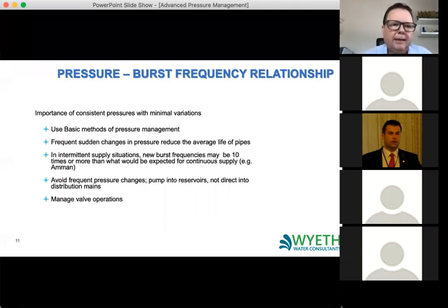When we're also looking at leakage volume, that is the first thing that we can look at with pressure management. But as I mentioned, burst frequency is another factor that a lot of utilities have to cope with. Especially utilities in places like Asia, where I work, you will often go to these utilities and they will have thousands of bursts or leaks that they're actually having to find and repair on a monthly basis. And a lot of those leaks are new ones that have occurred in the last month. So that's what we would call the burst frequency.